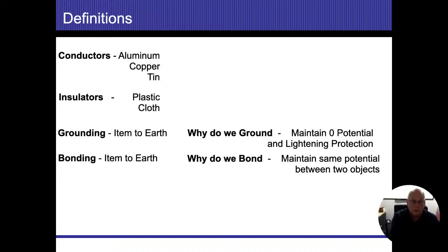It's going to flow into the earth. It's going to be about 5 amps. And I'm going to be on a 15 amp breaker. So that 15 amp breaker is just going to see 5 amps of electricity flowing. As long as it only sees 5 amps of electricity flowing, it doesn't know that there's a problem. It just lets it flow. It's not going to turn off until I try to flow more than 15 amps. That's when the breaker is going to trip.